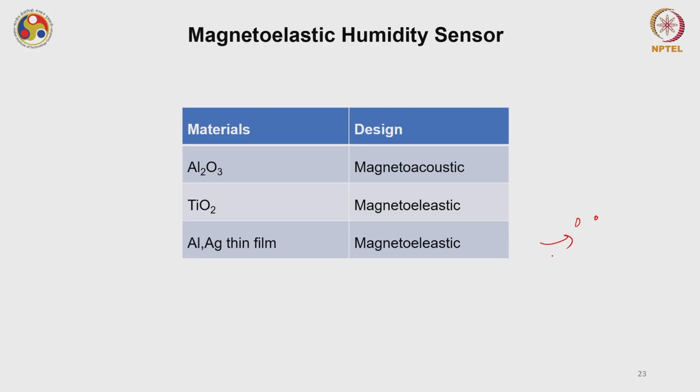Okay. So with this, I think we have covered several humidity sensors, which includes the optical humidity sensor, where we have discussed various devices based on multiple ways in which a photon can interact with the material. Say a water molecule can absorb the photon energy coming from a diode, or say laser, or LED, whatever you have as a source.